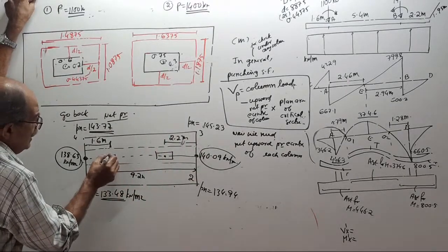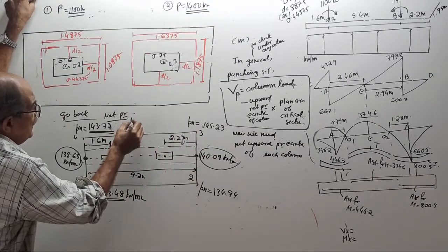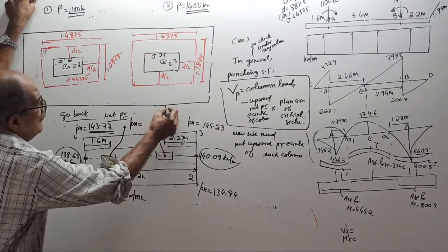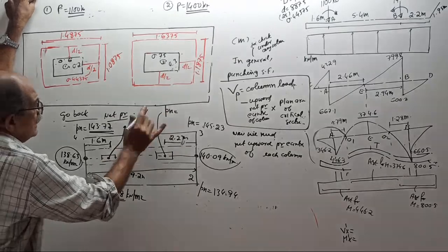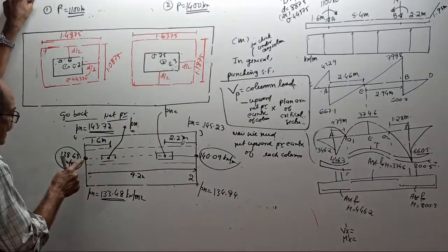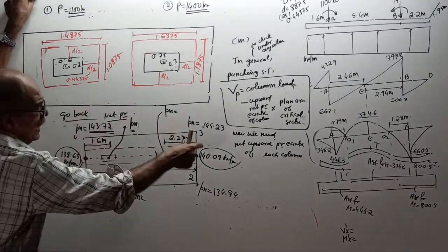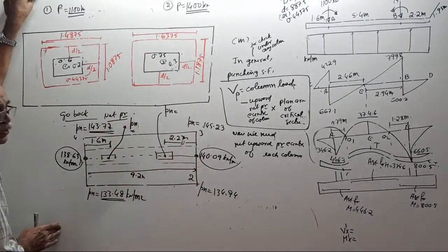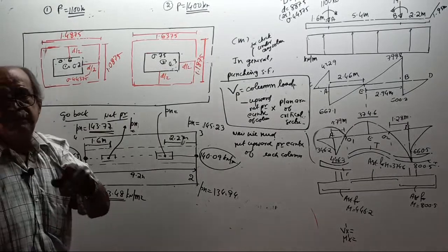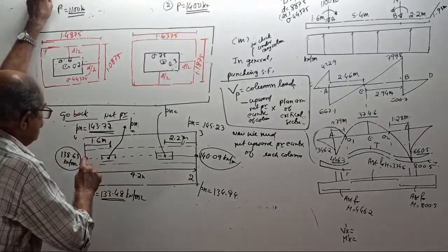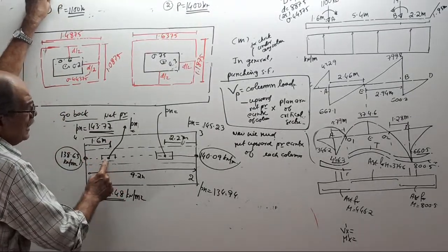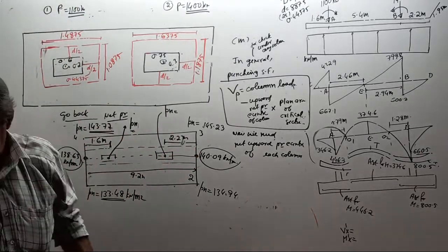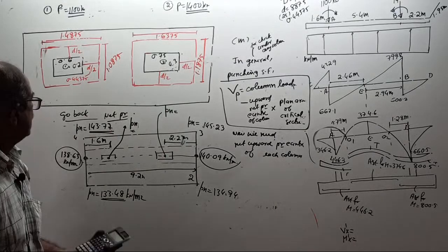Therefore tell me what is the net pressure here and also here by interpolation. Here 138.63, there 140.09, length is 9.2. We want to go by 1.6 meter, and here you have to come from that side by 2.2 meter. Answer, by interpolation.